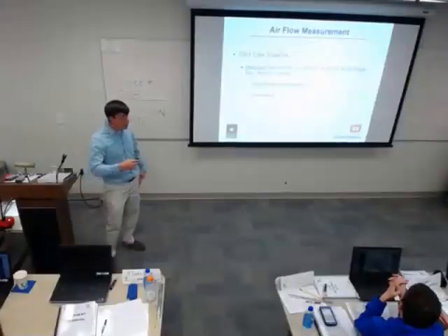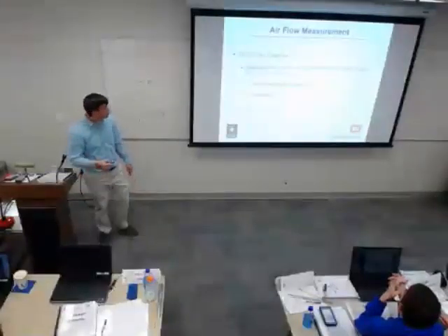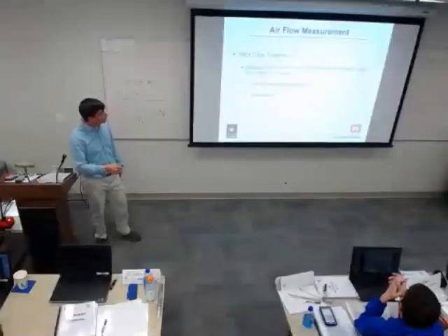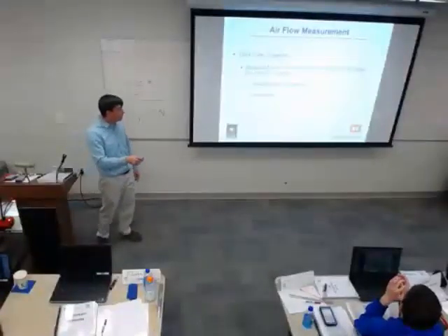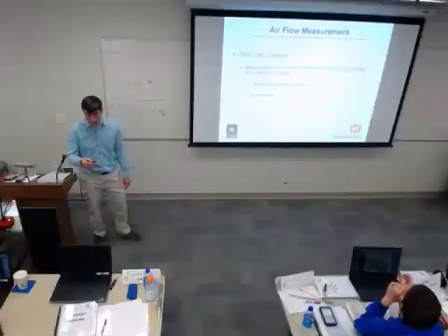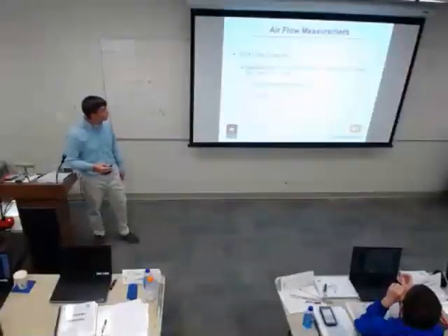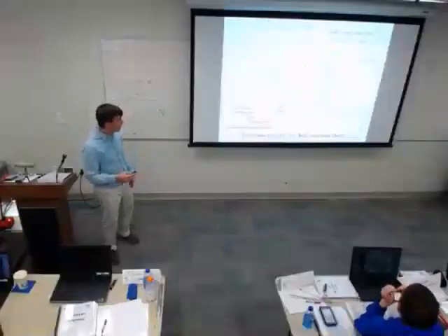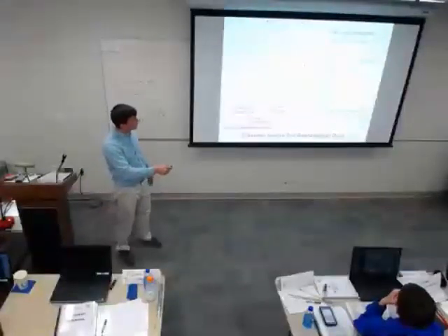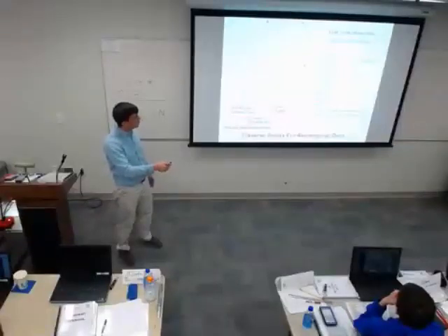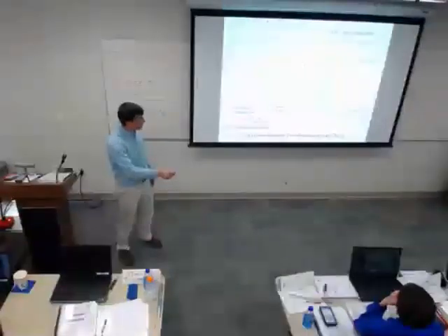All right, now we're going to talk in a little more detail about a pitot tube traverse. Just re-emphasizing correcting for density, and you may have to correct for altitude and temperature, depending on where you're at. And the TAB standard tells you how many measurements you have to have. So for a 4-inch duct, I need 2 holes. For a 100-inch duct, I need 10 holes.